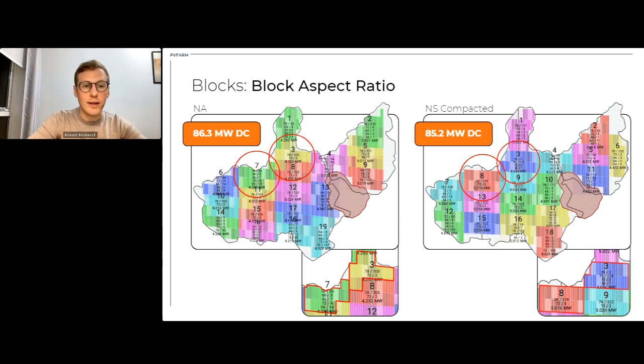You can see on the left one, the DC was maximized, basically. People demand those rectangular blocks, but sometimes they also demand max DC. So on the left option, we actually produced less rectangular blocks, but more DC, while on the right option, we lost 1 megawatt DC, which is more than 1% of this particular DC capacity for this project. However, the blocks are much more rectangular, and this is a good example of a trade-off people need to consider when designing layouts.